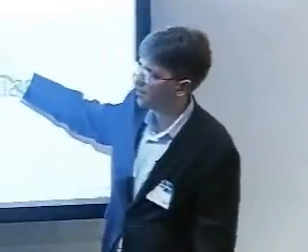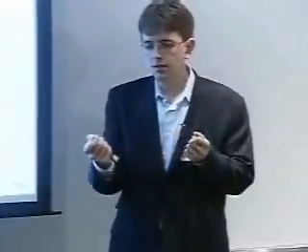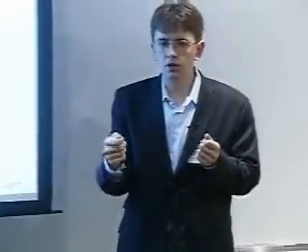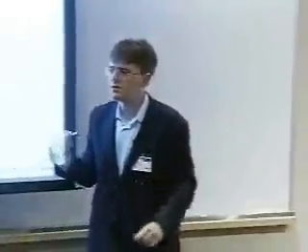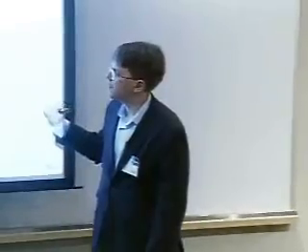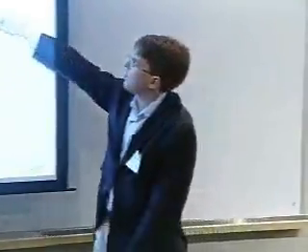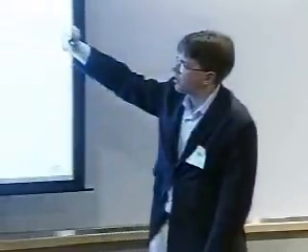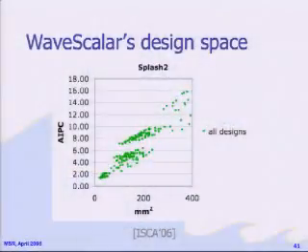We'll also apply some common sense rules. There are some designs that you can look at and just say, I can build a design that's strictly faster and no larger, or a design that's strictly smaller without giving up any performance. So we just throw out those kind of nonsensical designs. And then finally, we're just going to focus on the area critical parameters, the ones that have a strong effect on the output of this area model. If you do all of that, it turns out there are 201 reasonable WaveScalar designs, and that's a small enough number that we can just simulate all of them.